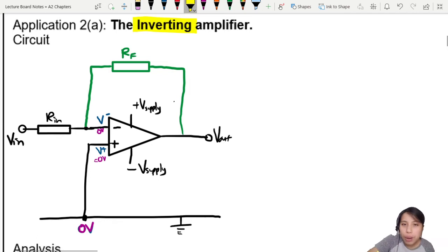Okay, so no matter what happened, remember you want stability. The loop will tell you one of these is 0, the other one must also try to be 0. So you match V minus and V plus to be the same. So whatever feedback goes on, going to make sure that that is 0. Okay, let's do a few more examples.